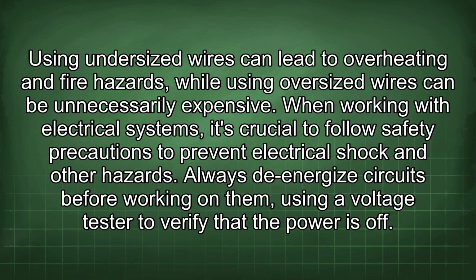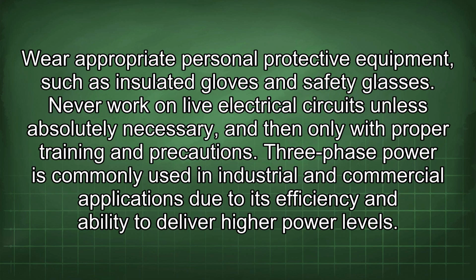Always de-energize circuits before working on them, using a voltage tester to verify that the power is off. Wear appropriate personal protective equipment, such as insulated gloves and safety glasses. Never work on live electrical circuits unless absolutely necessary, and then only with proper training and precautions.